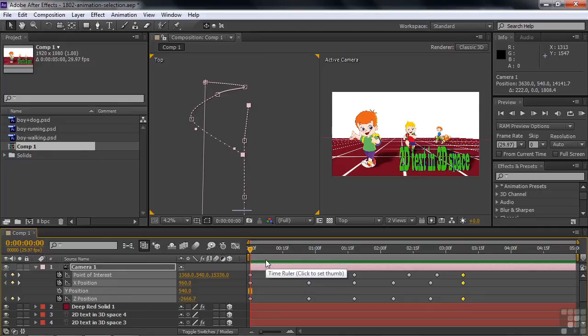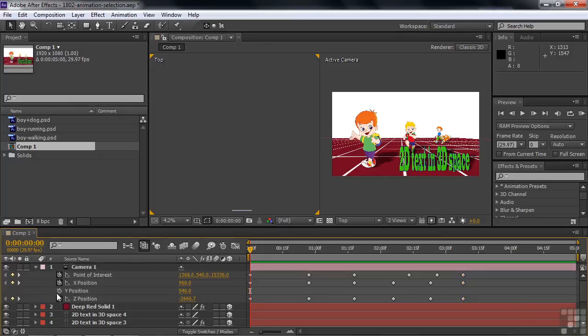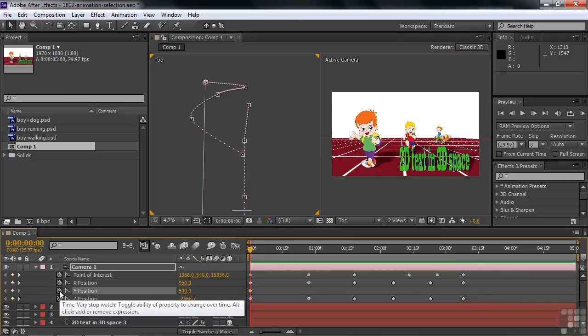We've got a camera on a track here, moving it through the scene on a track, using the X and the Z values. And now we're going to put it on a crane. We're going to lift it up above the scene with a crane, and Y acts as our crane. So I'll click away here like that so I don't select the rest of the keyframes. Click on the Y keyframe for that starting position.